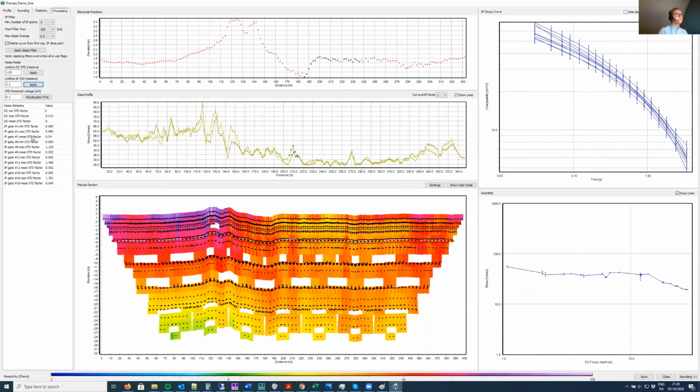And then we have the STD threshold voltage, which is in millivolts. What this does is that it will increase the size of the error bar of the standard deviation the closer the data points are to this threshold voltage. So you can use this to apply larger standard deviations to the data at the end of the decays.